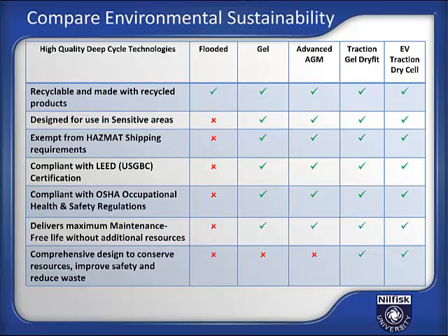So let's compare environmental sustainability factors as it applies to the 5 technologies. Recyclable and made with recycled products. This applies across the board, mostly related to the fact that battery lead is recycled and recyclable. Designed for use in sensitive areas only applies to the sealed valve-regulated products, gel, advanced AGM, traction gel Dryfit, and EV traction dry cell. Exempt from hazmat shipping requirements also applies to these products and does not apply to flooded. Compliant with LEED certification is also the sealed products.